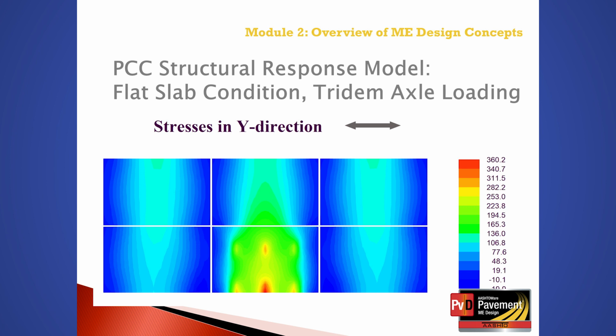This screen includes an example of the stresses calculated in the Y direction of the slab by iSlab 2000 across multiple slabs for a tridem axle load simulation on a flat slab without any curling between nighttime and daytime conditions. The highest tensile stress occurs under the center axle of the tridem axles and along the edge of the slab